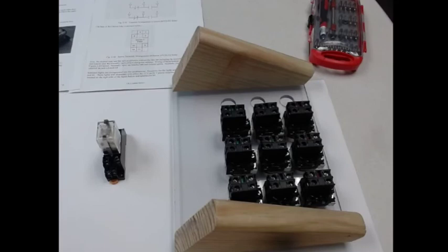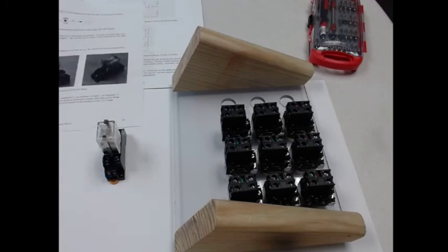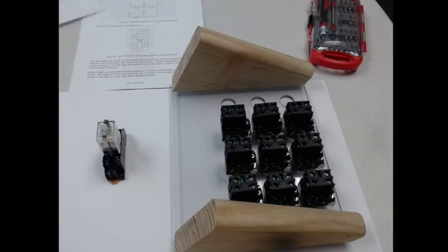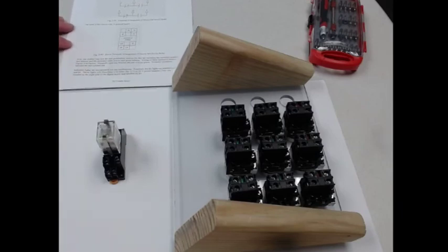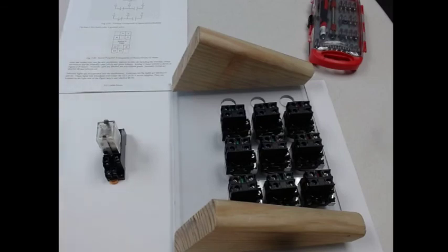So this is the relay that we're going to be working with in this lab, and it's found at the end of chapter 2. And this is the picture of that relay. That's on page 28. And then on page 29 of the chapter is this page right here. And in it, it shows the connection of the various terminals. So we see terminal 13 and terminal 14 at the bottom. So this is terminal 14, this is terminal 13. And we see if we wire the plus to 14 and the minus to 13, 24 volts, this relay will energize or turn on.